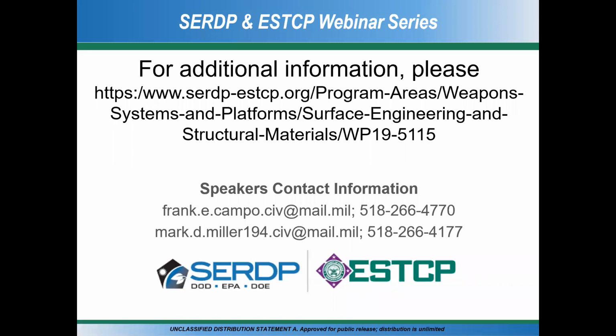I apologize. Well, you look on the periodic table, all the ones that have higher melting temperatures are viable candidates. What's difficult, and I don't know if people realize, is that the reason chromium was conventionally used is that chromium is the only refractory metal that's soluble in water. So just like table salt, you put chromium oxide in water and it dissolves. And if it's soluble in water, you can electroplate it. The problem with the other refractory metals, which have much higher melting temperatures, is that they're not soluble in water.